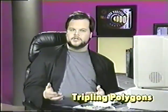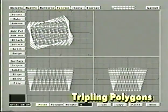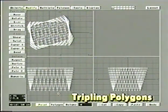And the way around that is by tripling the polygons. So one thing you might want to do if you start really torquing the polygons, really twisting or bending them, changing their shape quite a bit, is use the triple function. Keyboard equivalent is Shift-T. And the triple function can be found under polygon triple. What it does is it just turns the polygons that exist here into triangles. I'm not going to do that right now because I'm not done playing with this shape. But I'm just mentioning it: if you do something like this and try to render it, you might get some polygons that just won't render properly. So you'd want to use triple there.